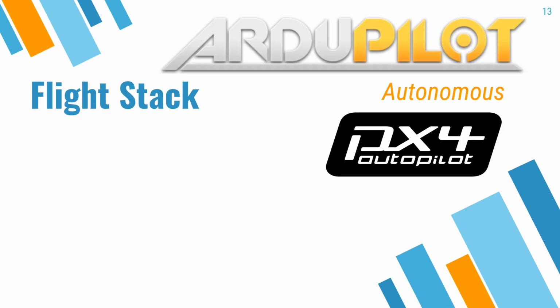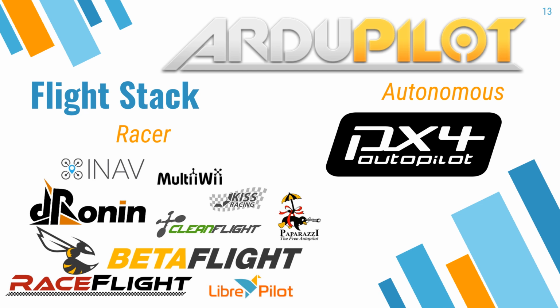In order for a flight controller to work, it needs software. That's why each flight controller has its own software stack or flight stack. For autonomous flight controllers like the Pixhawk, you can either use ArduPilot, which is the most popular one at the moment, or PX4 Autopilot, which is from Pixhawk itself. For non-autonomous flight controllers, so usually for racers, there are a lot of different ones, and each flight controller specifies the software stack suitable for it.